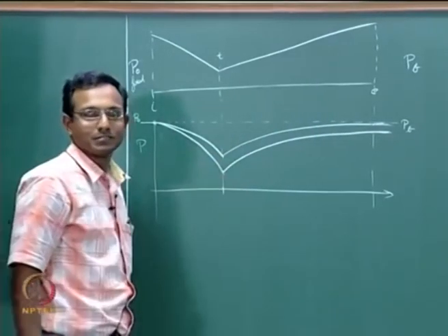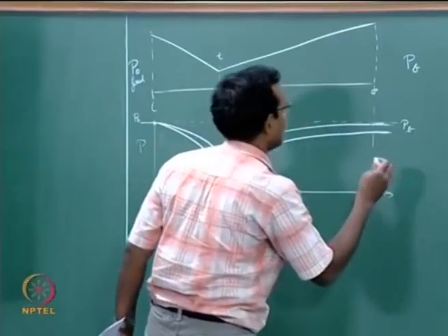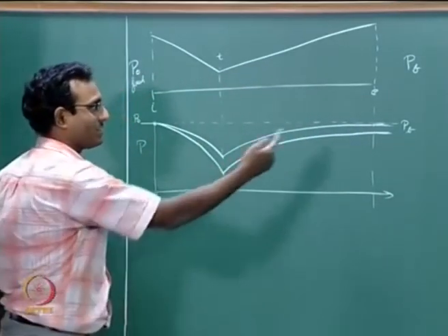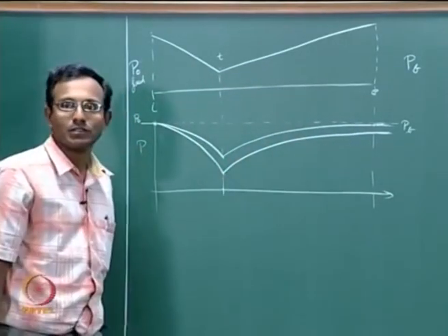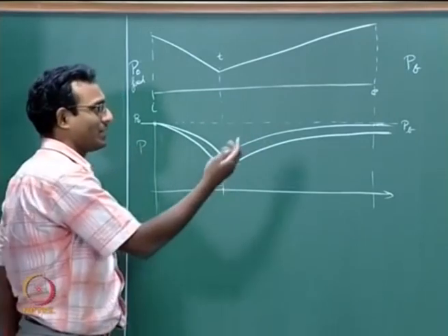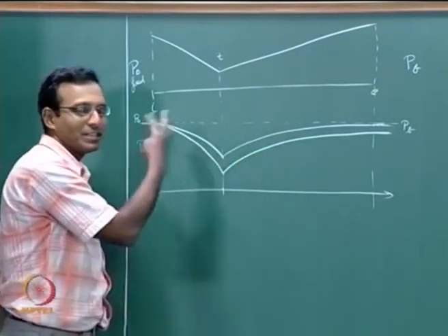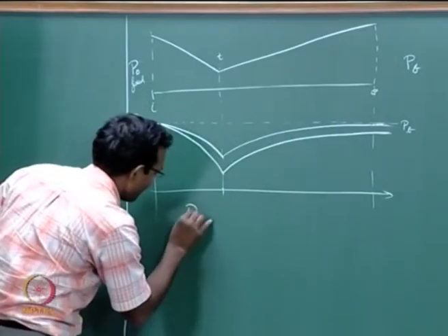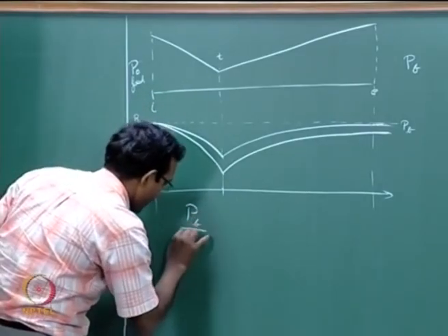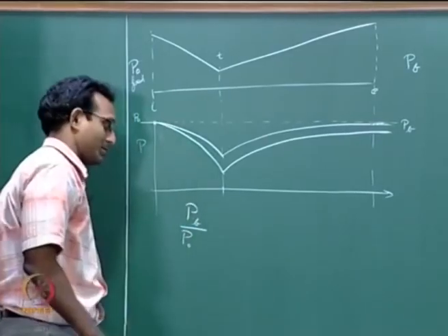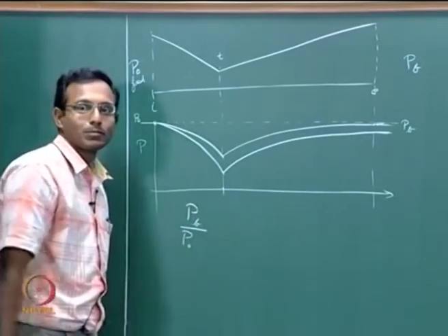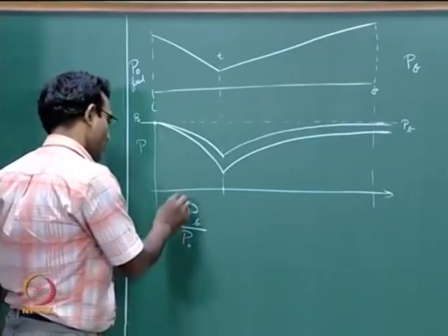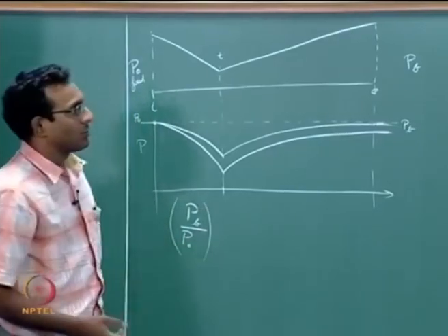Now depending on whatever is my Pb to P0 ratio, the final pressure in the middle will be decided. So to decide this problem, what matters is just this ratio of Pb to P0, these two numbers, P0 and Pb, and typically we write it as back pressure divided by stagnation pressure. This ratio decides this problem. Okay. So let us go to the screen.